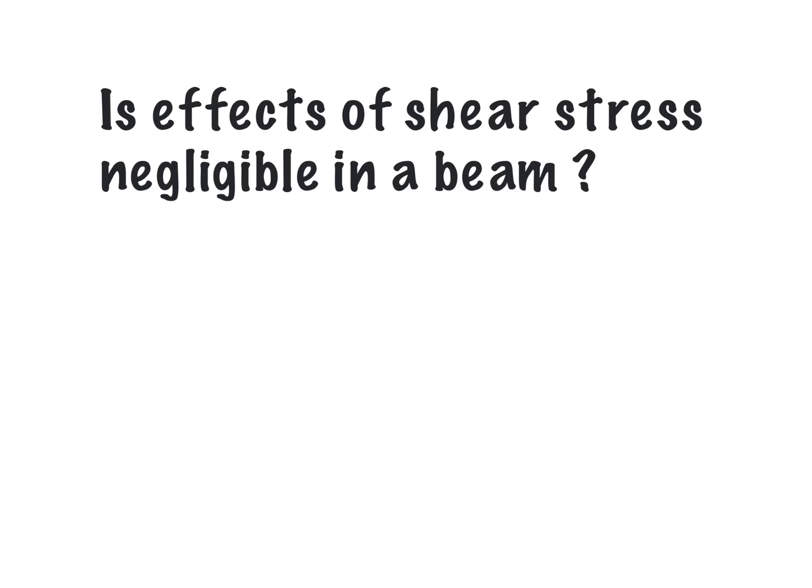But even then, most textbooks use Euler-Bernoulli theory. Not just textbooks, when you start working in industry as well, they use this Euler-Bernoulli equation left and right in many practical scenarios to calculate the stresses due to bending. So why is it? The obvious reason is that the effect of shear stress is negligible in a beam compared to the bending stresses. Now can you go ahead and prove it? Hold your thought, I will do that.